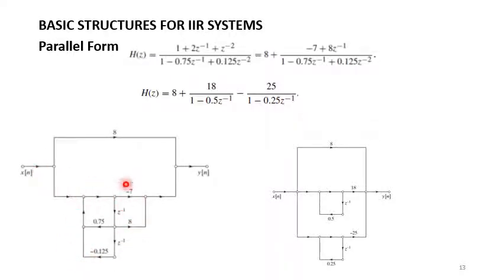So we have zeros, so just simple scaling. We just write minus 7, and then we have scaling after delaying by a unit delay. So we have just delayed it by a unit and then scaled it by a factor of 8. So I hope that's straightforward.